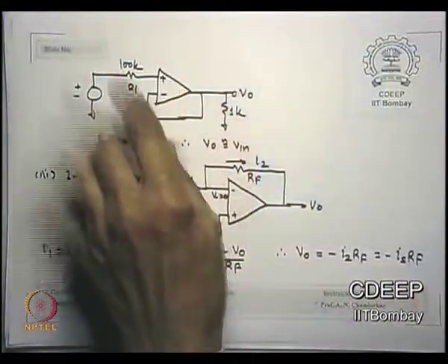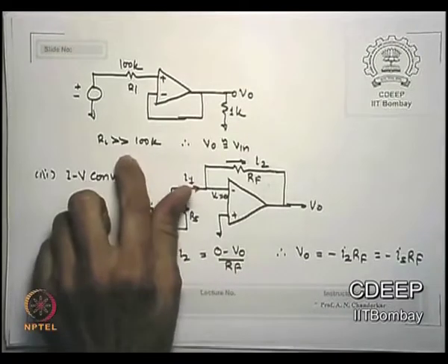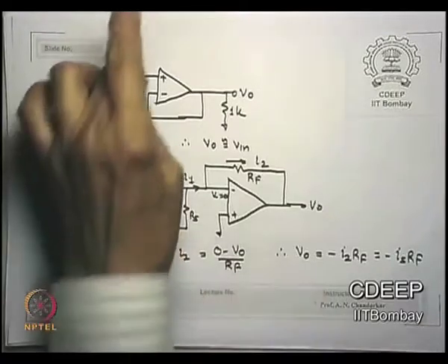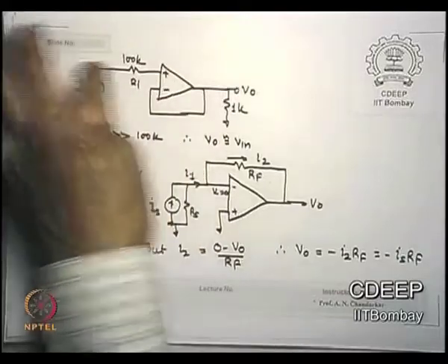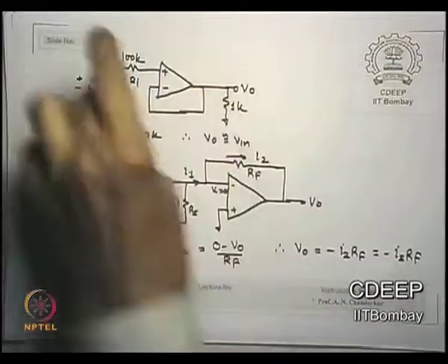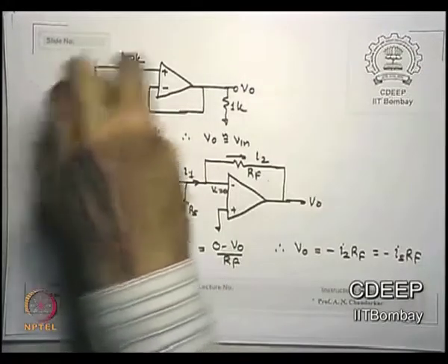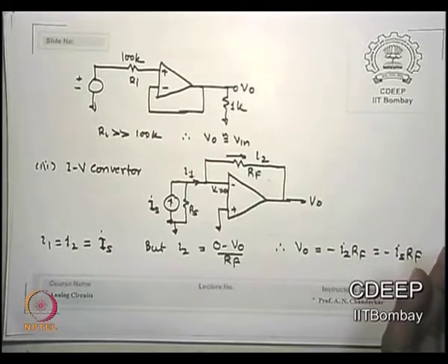So here is something I say: let me put in a voltage follower, with a 100k here. The output coming here should be the same, at least that much I should get. Now what should the condition be? The input resistance should be at least more than 100k, then it will not load. If this resistance is more than 1 megaohm, then its current matches, nothing will enter it, so only the voltage will appear here, which is followed at the output. Is that correct? If this resistance is very, very high, which is what the op-amp will provide, it will only create a proportional voltage with no current passing, so no drop here. No current passes in the 100k, so this voltage appears here, is followed as it is at the output, and it does not worry about what resistance you put at the output. This is buffered.